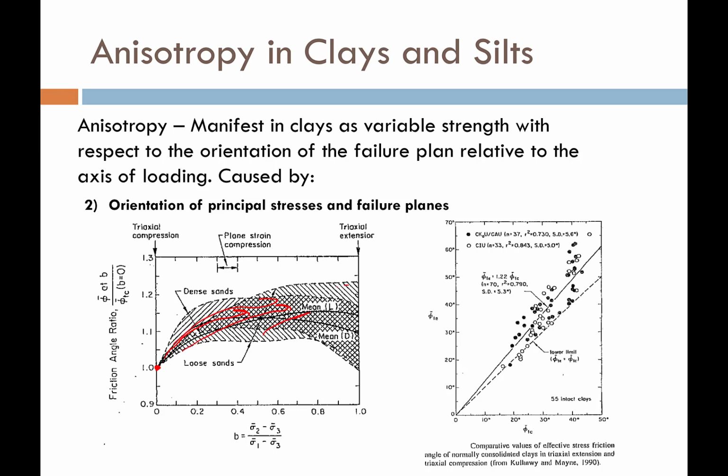And so now we're in ratios anywhere between about 5% higher to about 25% higher. So this is where that 1.05 to maybe, that looks like about 1.23 or so within that range. So that's where that 5% to 25% comes from. And all of that is because as you move towards axial extension, you have a larger mean stress in your soil.